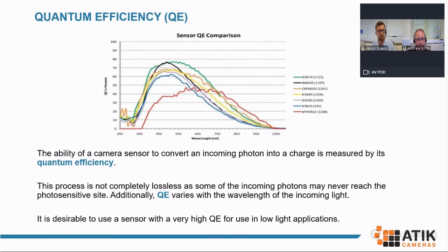So we must instead be mindful of the fact that these sensors do have varying performance across the full spectrum. As we can see in the graph, it will change quite dramatically depending on the wavelength. A lot of the sensors that will be readily available tend to operate quite effectively in the visible spectrum, but you will see a very rapid tail off in the UV and towards the infrared ends of those spectrums.